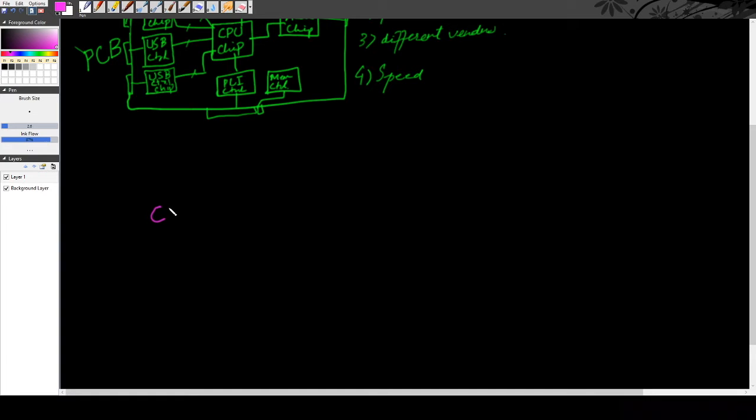Okay, that's good. So we buy a CPU chip from one vendor, and we create our own chip, or we buy from a vendor with all the IOs and IO controllers that we need. For example, Intel calls it a peripheral controller hub. So let's call it PCH. This has USB, hard disk controller, HDMI, PCI, VGA, all those things. And then for accelerator, we still use a separate chip